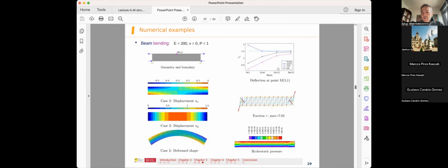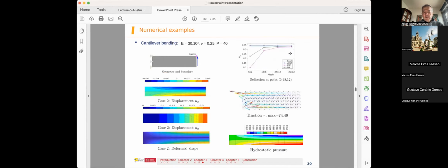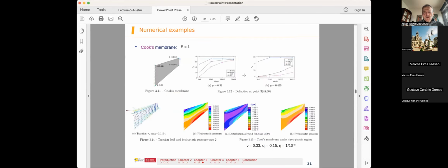This is the constant strain triangle, or 4-node element. And then here you already have 12 times 6, basically exact, while the other guys take much more refinement in order to converge. But the statics was only part of the story we actually wanted, and this is now the cantilever beam where you have this bending. Again, this one goes perfectly well, immediately converging, because it's suitable for this bending part, as opposed to the other guys that take much more mesh refinement to converge.